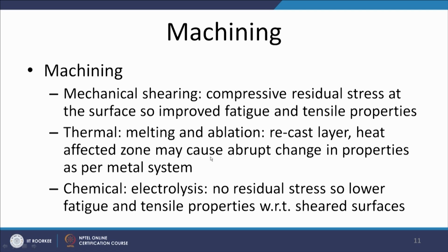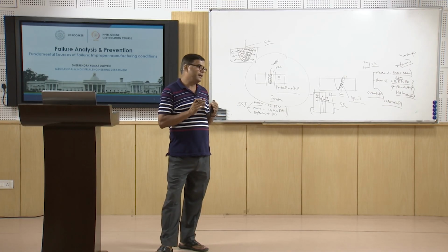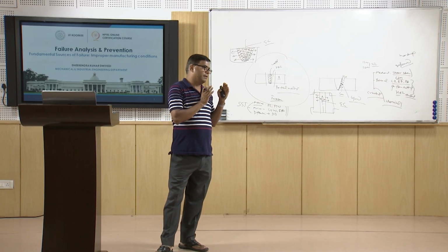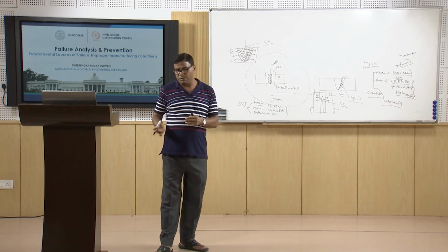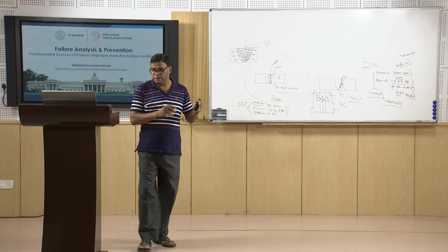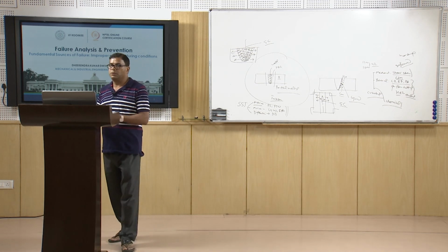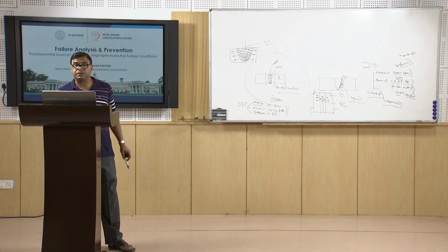So, these things will lead to a lot of metallurgical and mechanical heterogeneity, especially near the surface layer. If such components are subjected to fatigue loading or high tensile loading, especially with residual stresses, then these promote the nucleation and growth of cracks, which in turn promotes the premature failure of the component.